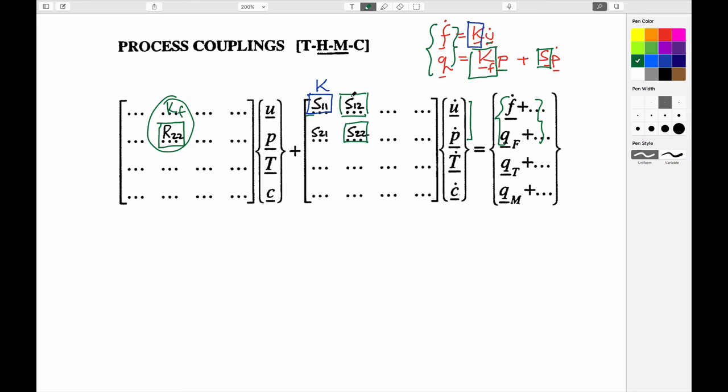And what we'll find out is that because this expression has to be written in terms of all apples or all oranges, the apples have to be units of force. This is units of rates of change of force per unit time. Then this has to also be a force per unit time that results from the product of this times the pressure. And so this term here we can think of as a body force that adds into it the effects of the fluid pressures as a body force, which the solid mechanics expression, really an equilibrium equation, can accommodate. So that's the first part.